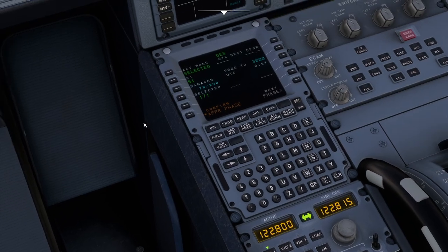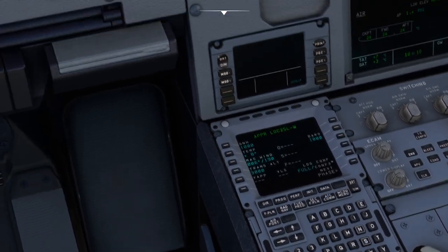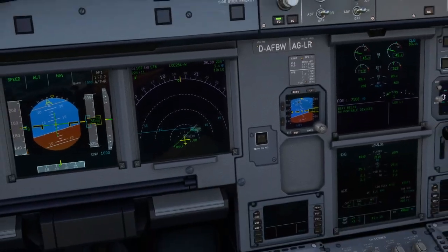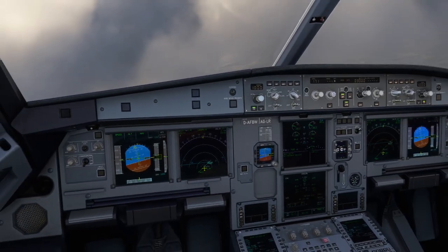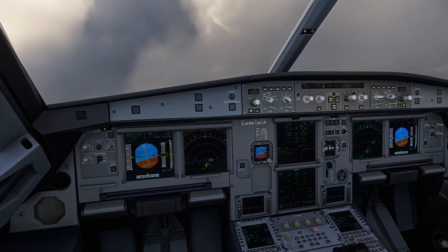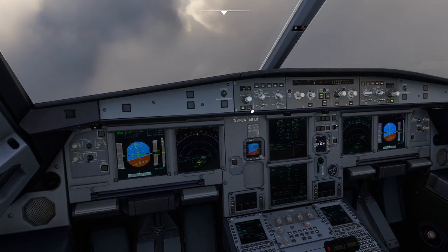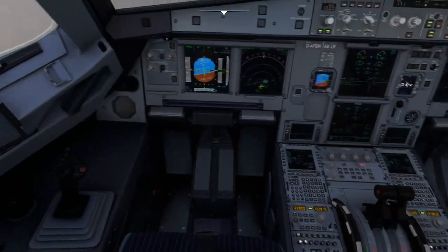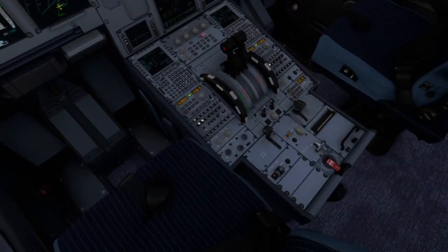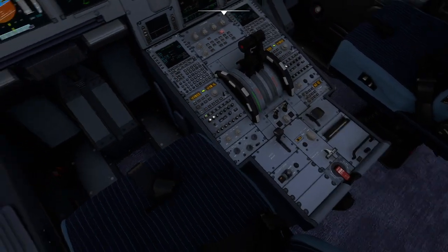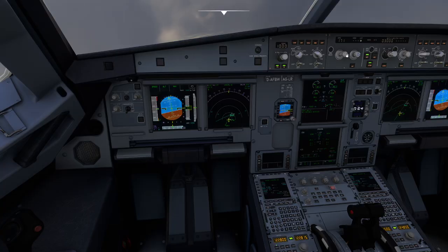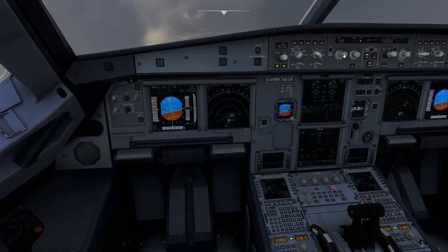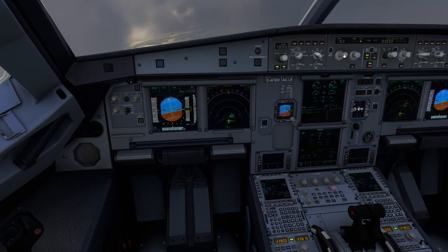Now I'm activating the approach phase. I'm turning. Pushing traffic, Ryanair 44 Bravo, runway 25 right, line up and take off. And my speed is 160 and I put flaps 2 and I can reduce further to maybe 140.